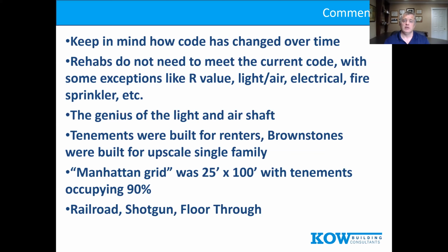They were legally non-conforming. And then the city said, you know what, not so fast. Let's require this and give people until 2020 to do it. So buildings over 10 stories that are office buildings, you're no longer grandfathered in if you have fire sprinkler coverage. So that's a difference of where the city said, we're okay with some things, but some things we're going to make you do even if you weren't going to do a renovation. And a lot of times what will happen is the heavier renovation you do, this is really anywhere, but certainly in the city, more things will kick in that are required.